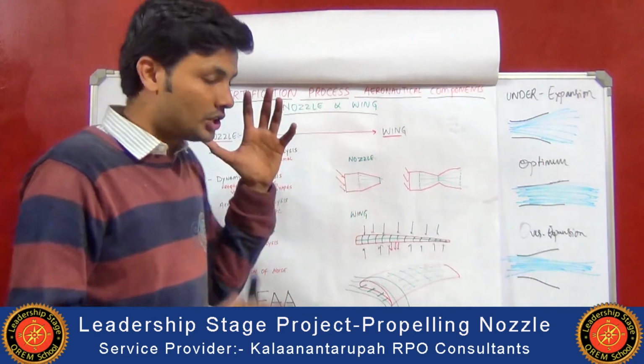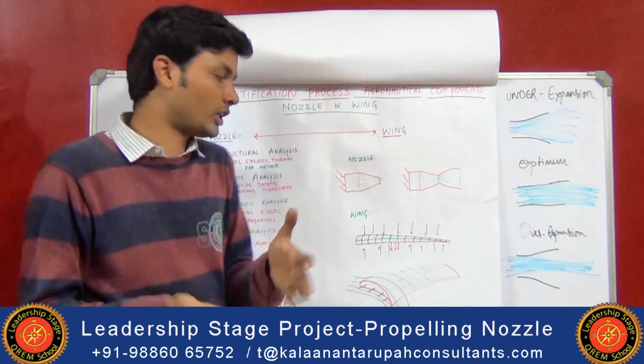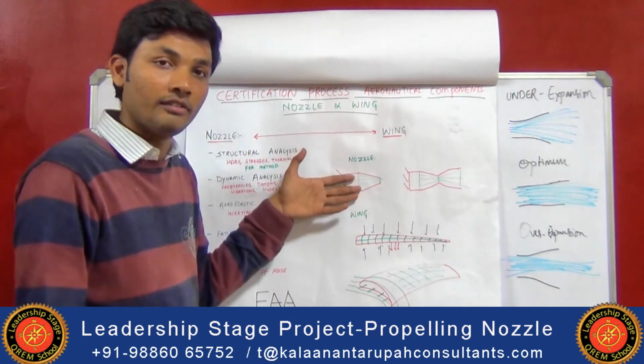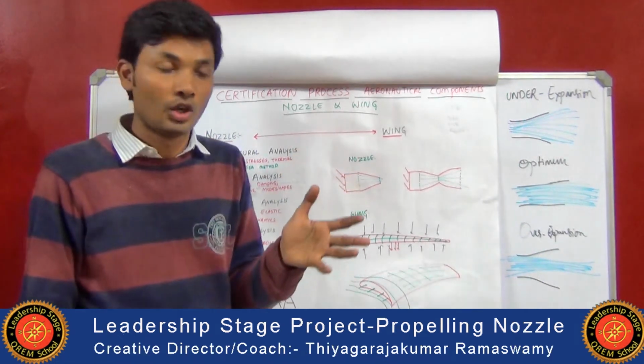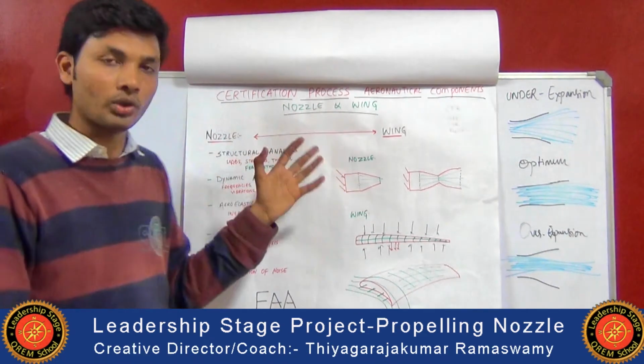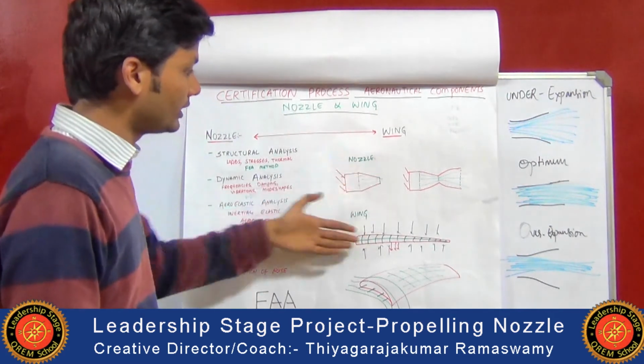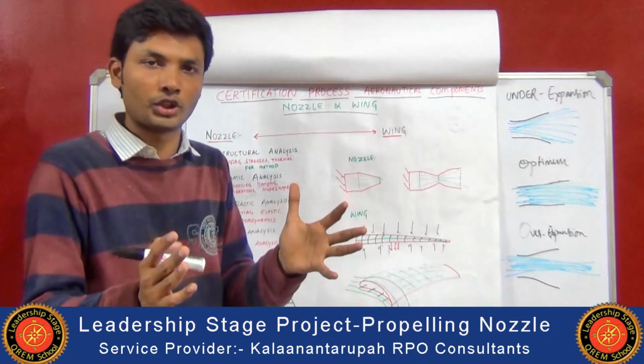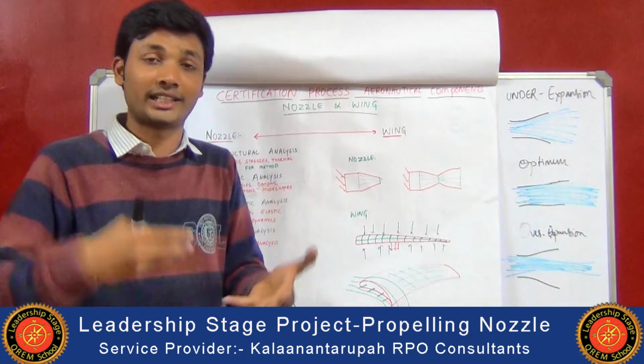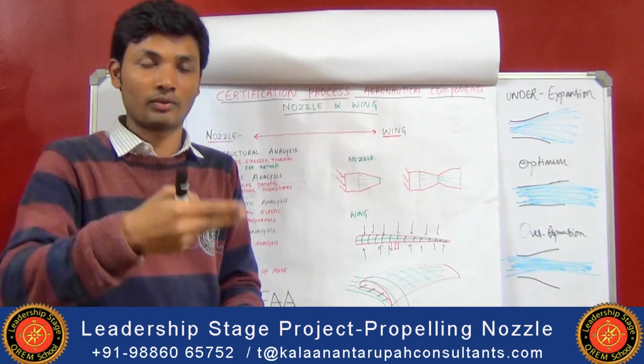But over here, changing the thrust direction because of damage or deformation of the nozzle is a different thing. So we have to stop that and control that. We have to see that the whole design of the nozzle is within the limit, so that it does not get deformed under the actual extreme loads being applied on the nozzle. So we have to check that.